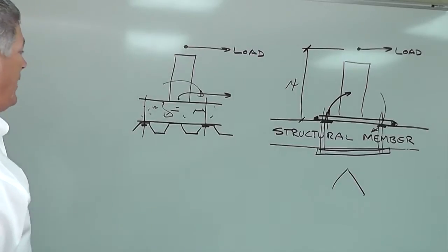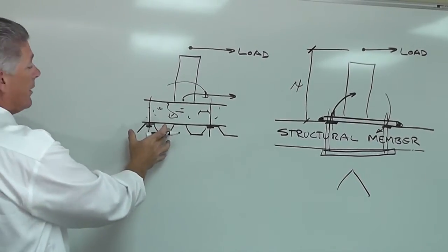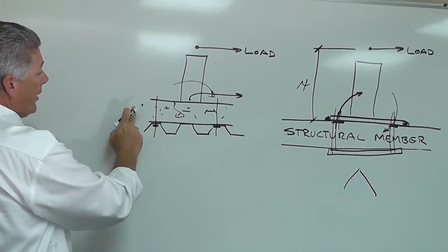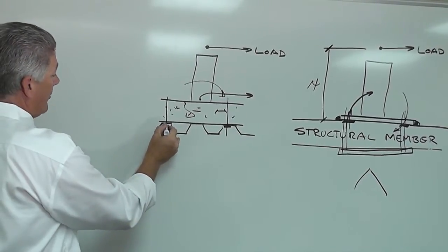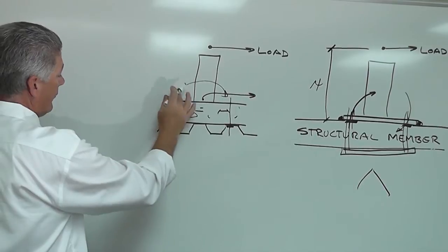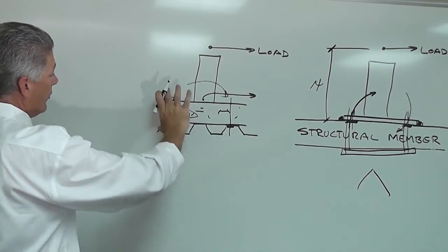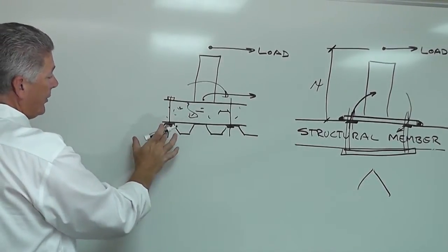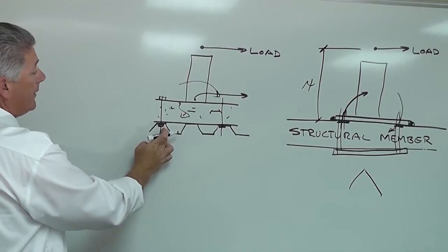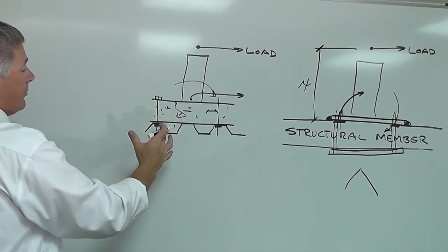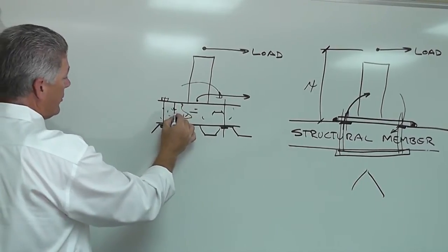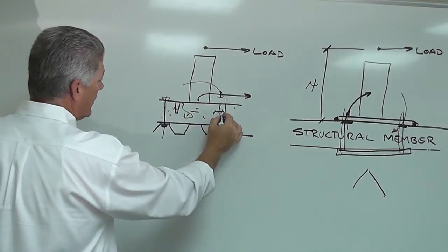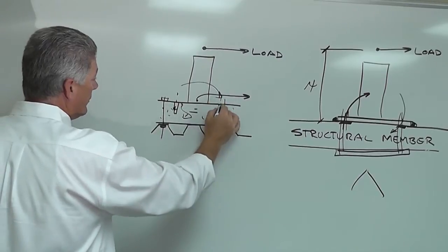On tip-over technology, although what we're showing here is a standard built-up membrane roof with metal deck below, we're utilizing a toggle mechanism where the 4 holes that you drill down through will compress all the roofing material to the deck. If this was going to be used in a concrete deck, there are specially designed anchors that you embed into the concrete and you bolt down through those.